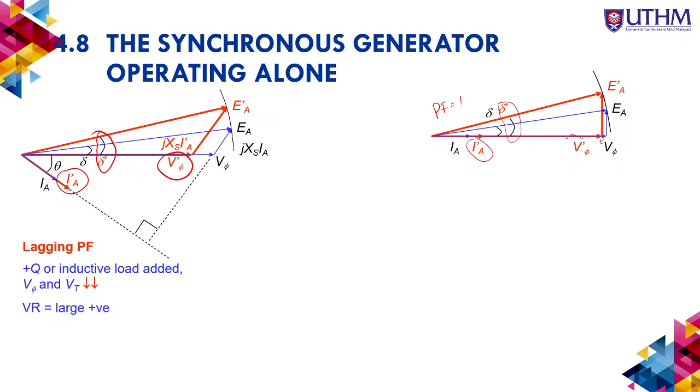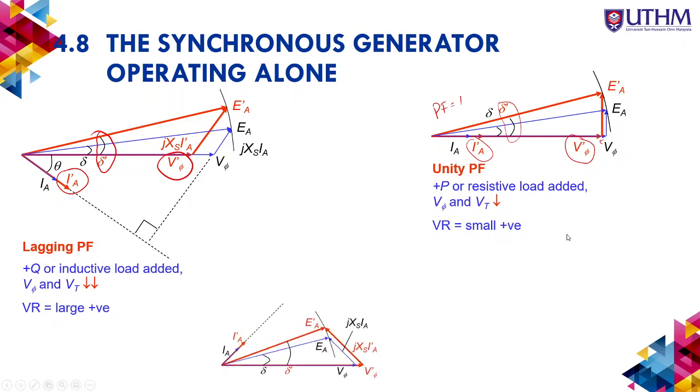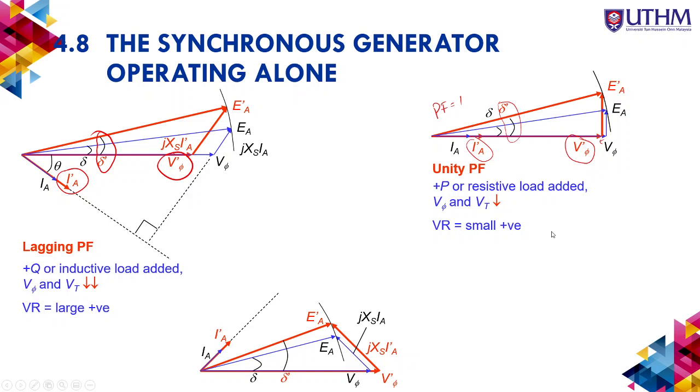So these three parameters will change for the unity power factor. The voltage will drop, but only slightly, so the voltage regulation is a small but positive value.